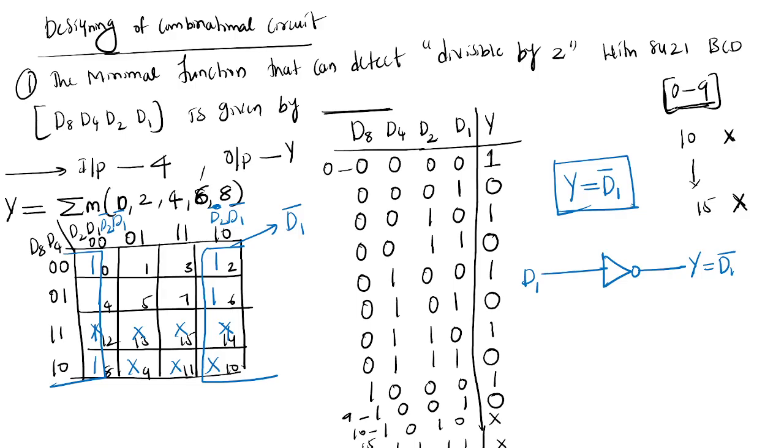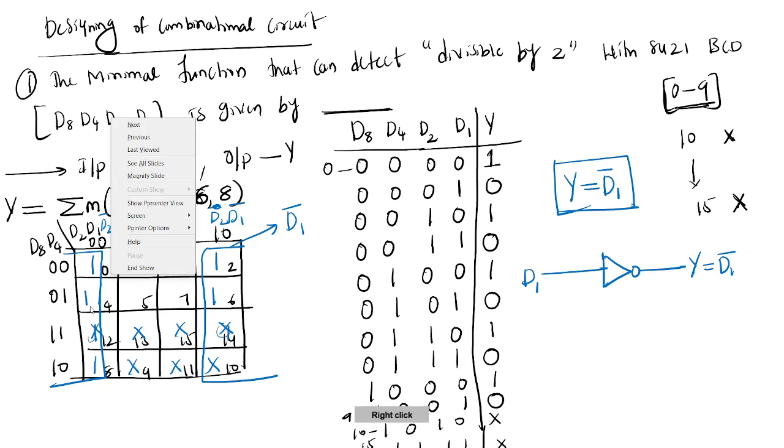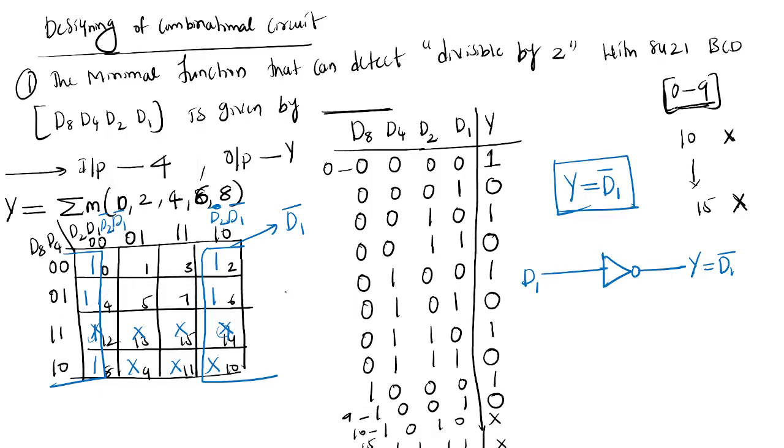It could also be zero, no, sir? But depending on the possibility, in the K maps we already discussed. Suppose you consider this as zero, you are getting this one quad, two quads. Two quads means two prime implicants. Suppose I consider these two as one, I will consider this as zero only. Then one more prime implicant. So this one I am considering as one, I am getting one octet.